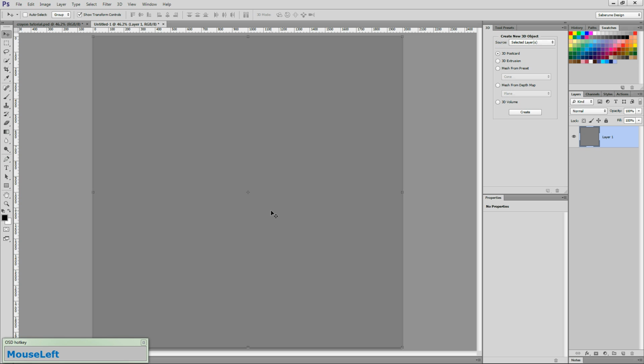Now it's time to lay out the guides. Toggle your rulers to visible by clicking Ctrl R. Right-click on the ruler and set its dimensions to pixels. Next, left-click directly on the left-hand ruler and drag out a vertical guide and drop it on pixel number 1000, which is at the center of the canvas, holding Shift as you do to snap it to the pixel grid.